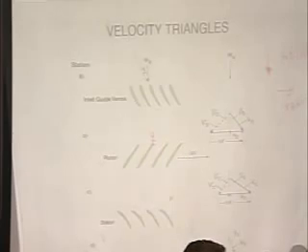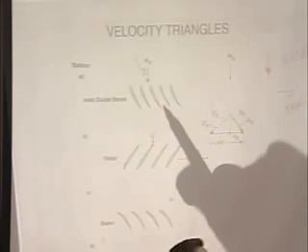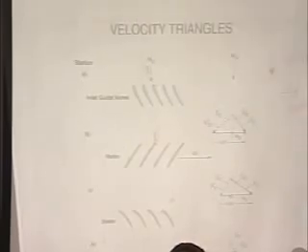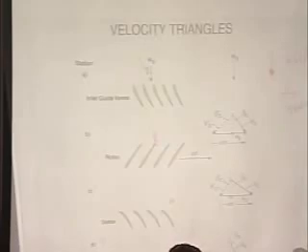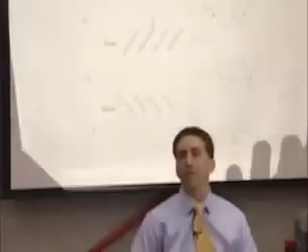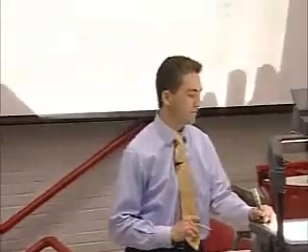You have to put yourself in the frame of reference of sitting on an airplane's wing. The higher the alpha, the higher the angle of attack. But that's reasonable. You'd expect to have a positive angle of attack coming into these blades. If it were negative, you might worry a little bit that something was wrong.